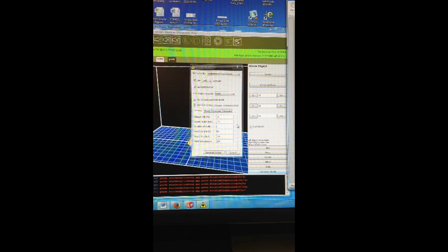The feed rate is the speed which the printer head moves over the base. For ABS, it is typically 80 millimeters per second. The print temperature for ABS should be between around 220 to 260 degrees Celsius. It is recommended that at the accelerating speed, it should be 235 degrees Celsius.